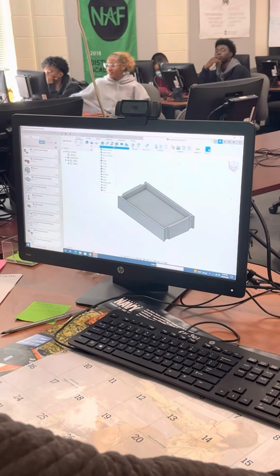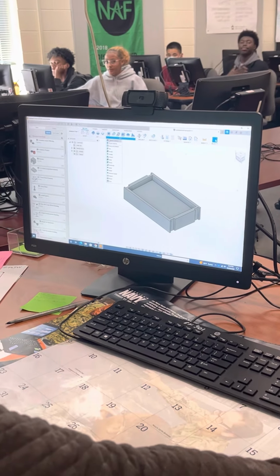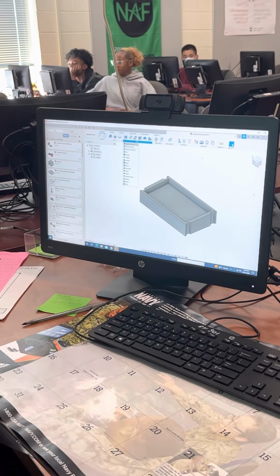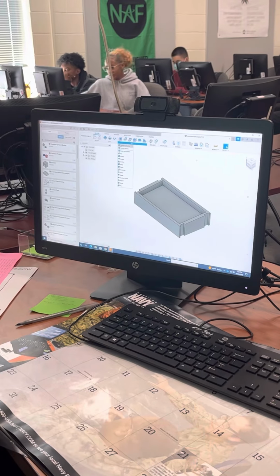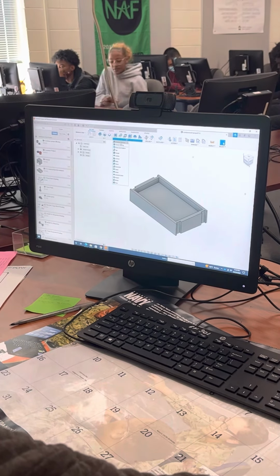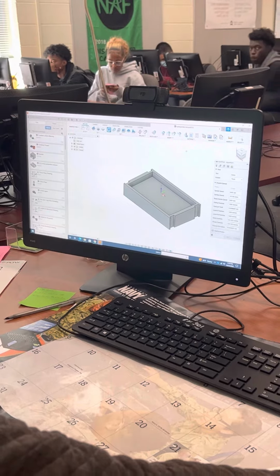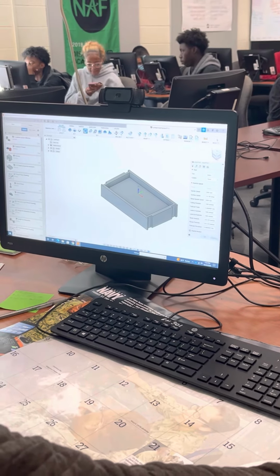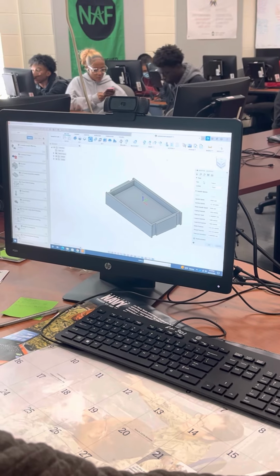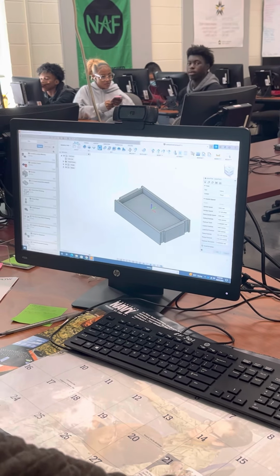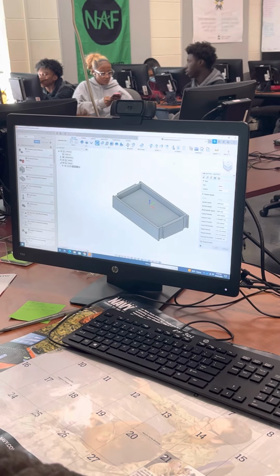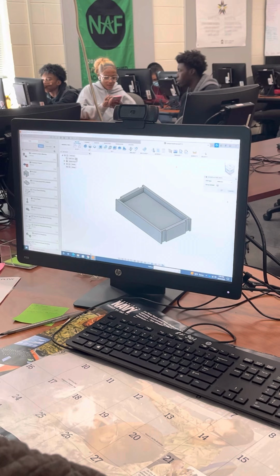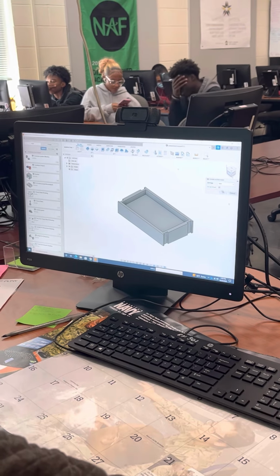Thank you. So you can see in here, these are the same tools from my video. In the portfolio guide, I gave you CAM 1 and CAM 2 videos. These are the same tools, same process. So I'm just going to use adaptive clearing. This X, Y, and Z has to be relocated. You probably want to put the units in inch mode too. So up here, you can just go back to inches.